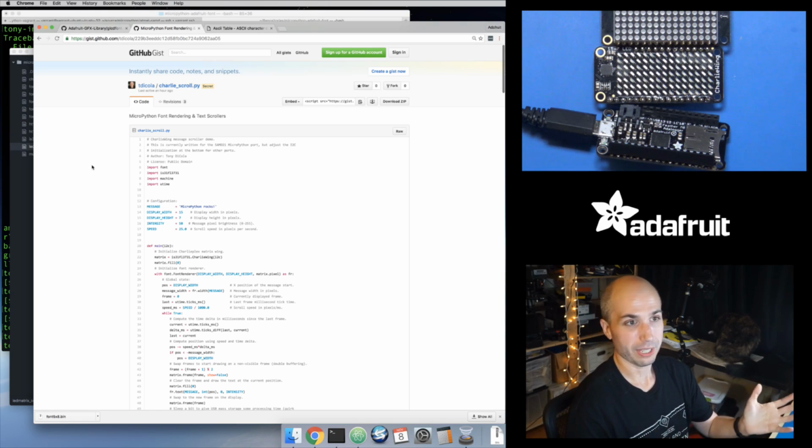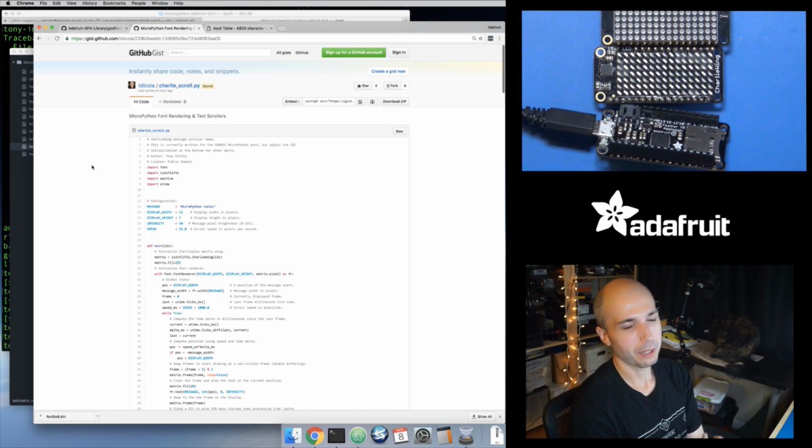First of all, what is the memory allocation error? As you saw, if you get back an error, memory allocation failed, you've probably got too much stuff loaded. And so then you really need to think about, how do I optimize my code so that I'm not loading things into memory? In this case, I optimized it by saying, well, my font doesn't have to be in memory. I can throw it in a file, and then I'll just seek to the position in that file that I care about.